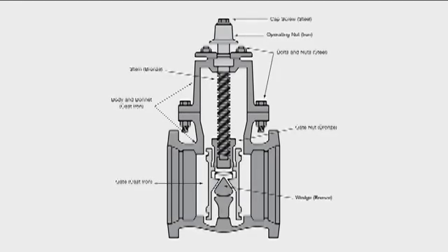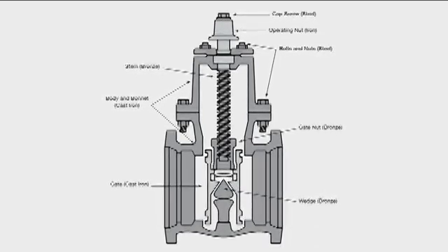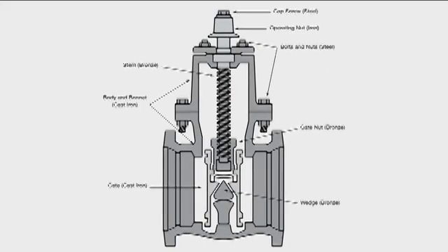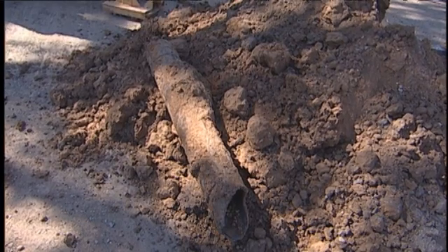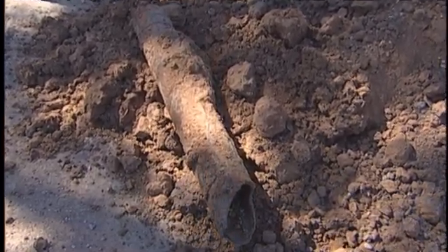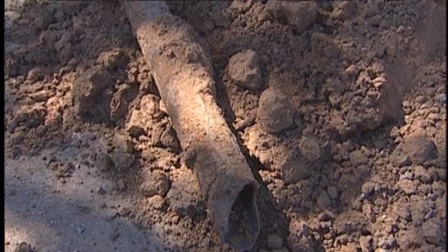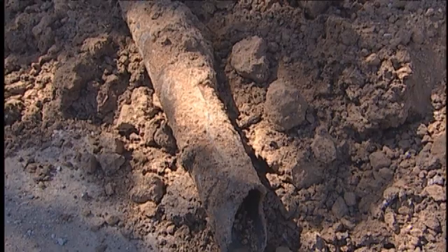For example, this valve is made of several types of metals. In the absence of a protective coating, a galvanic cell can develop and corrosion will occur at the anode. Pipes can also form galvanic cells. Surrounding soil containing water forms the electrolyte. Variances in the soil or pipe composition can create electric flow and corrosion at the anode.